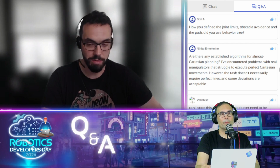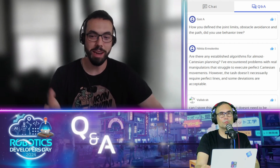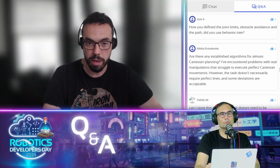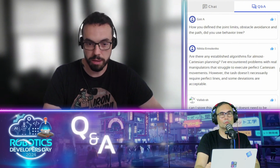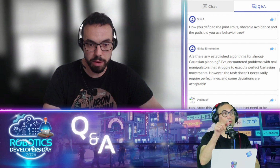But if not that, you can also ignore the URDF and use your own limits based on the knowledge you have for your robot. Maybe the manufacturer said these are the limits, but you want to run slightly slower to be conservative. So I think most tools let you either read from the description file or bring your own limits. Same for obstacles, right? You can have the obstacles live in the URDF, or in the case of one of these other examples, we actually, let me go to a different example here.